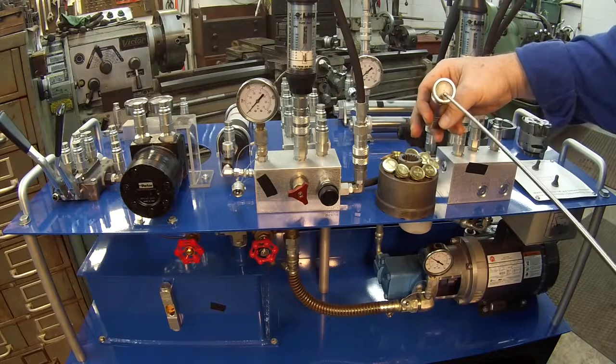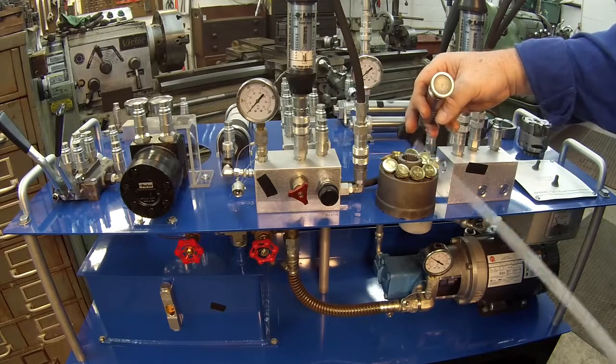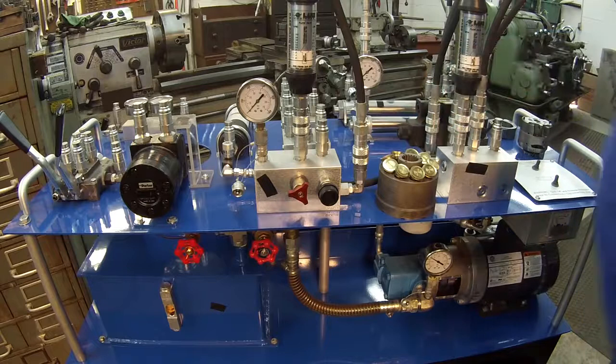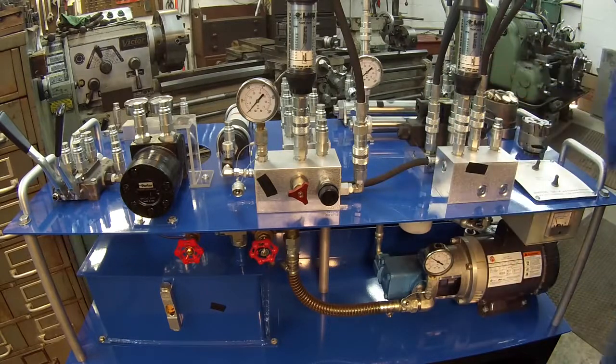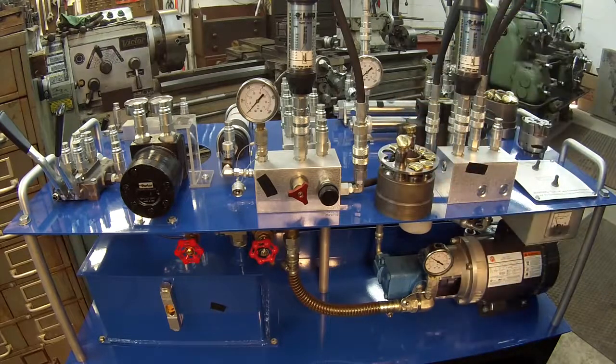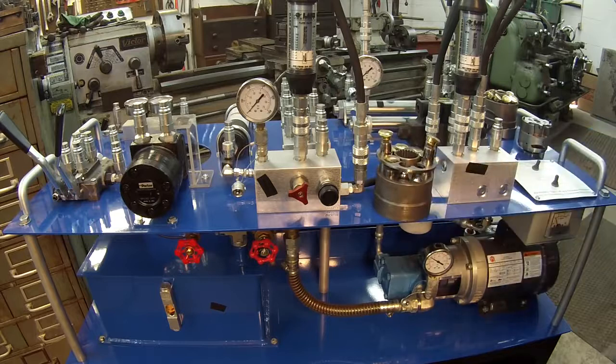Okay? When you starve your pump for fluid, that oil doesn't come through that little hole right there, and you get what's called cavitation. Okay? And as your pump cavitates, this is what happens to it. Those little pretty brass shoes melt. Okay? So as those brass shoes melt and disintegrate, obviously all that metal right there is going somewhere, and it goes out into your system and starts getting into your valves and actuators and your seals and all that sort of stuff.